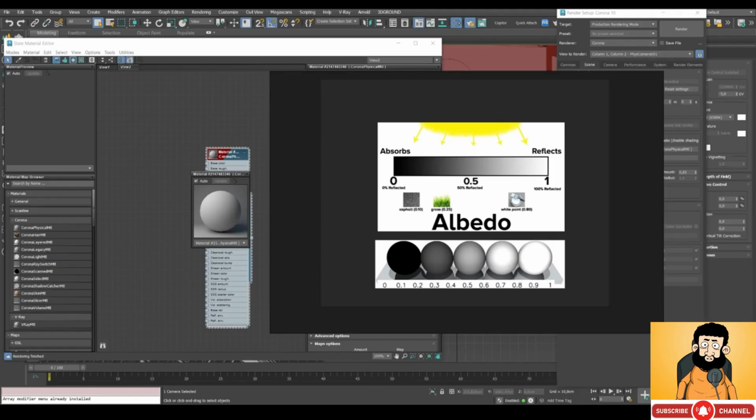Now you shouldn't make your materials too light. You shouldn't make them too white, because otherwise the graphic engine will take forever rendering your scene. You'll have to deal with artifacts, highlights, points, and things like that. The graphic engine will take too long getting rid of all of that noise. So don't underestimate the importance of albedo.